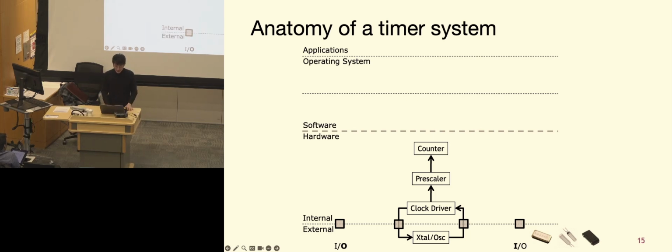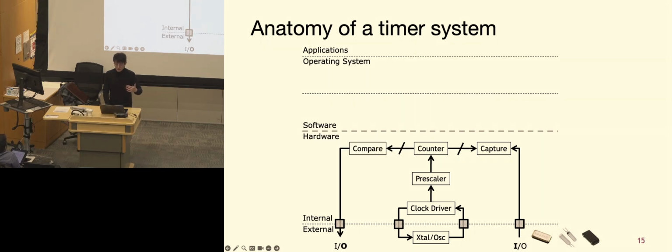And then we have the capture or compare register. It usually holds a predefined value, and when the counter matches this value, something occurs, something happens. If that sounds quite familiar to you, you're probably thinking about the right thing, which is interrupts or some of the output signals that can be triggered at a hardware level.